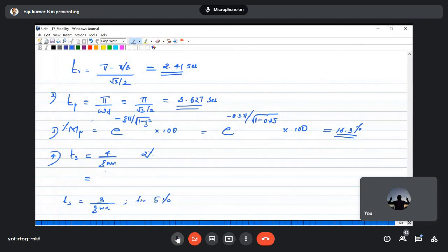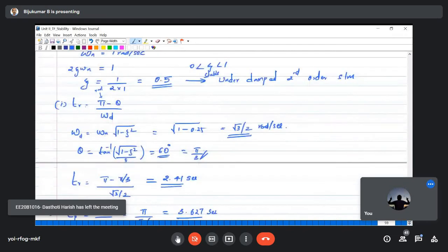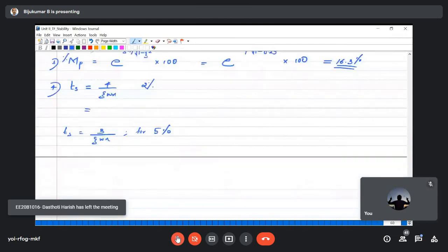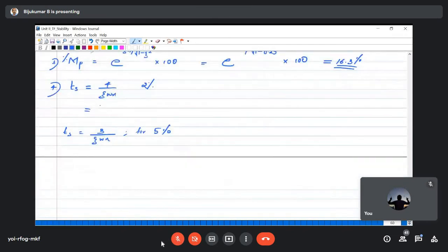What is the value of settling time corresponding to 2%? 8 seconds, yes, good. And what about 5%? 6 seconds, sir. 6 seconds, yes.